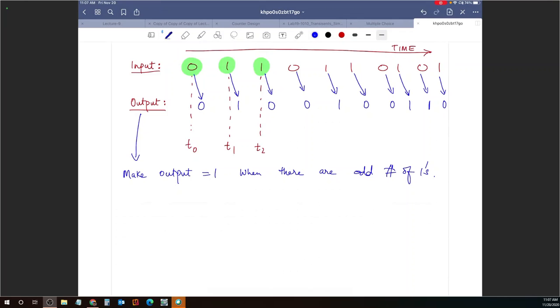How many bit input do I have? Oh well, 9 because I have taken 9 examples. But is it a 1-bit input or a multiple bit input? 1 bit at a time, right? So my input is essentially 1 bit input, 1 at a time. So it's just 1 wire, but the value on that wire is essentially changing with respect to time, right? So it's a bit stream. It's 1 bit getting streamed.